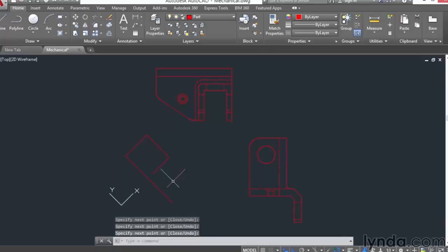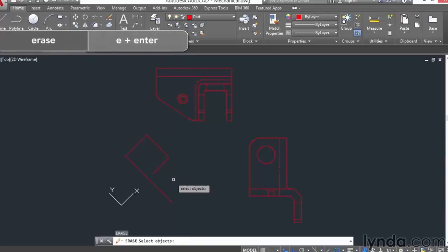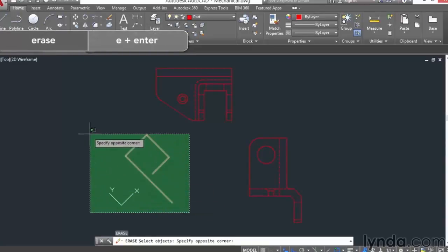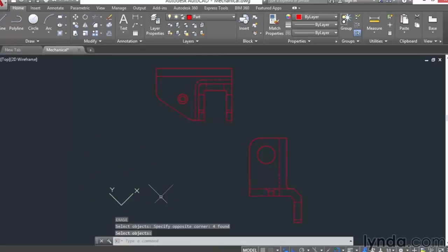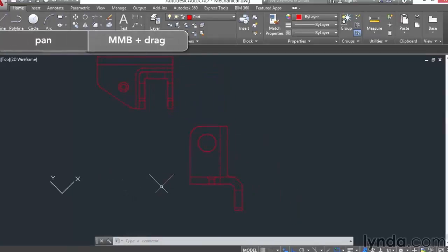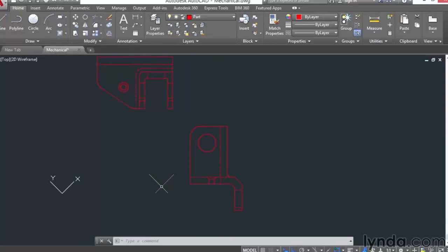And so this can come in handy if you're trying to draw something that's at an angle. So let me just erase these. Notice that you cannot erase the UCS. It's a drawing aid that remains on the screen. You can turn it off, but you can't get rid of it. I could type UCS icon off, but I would still have the benefit of this rotated coordinate system.